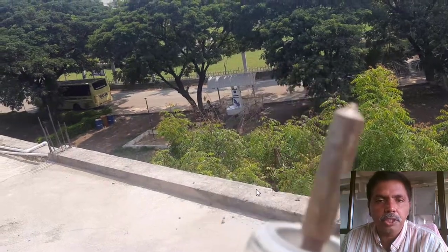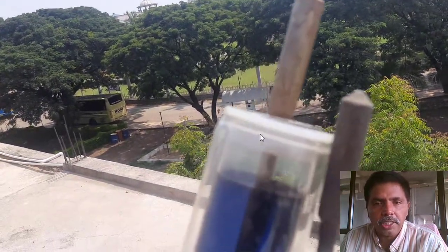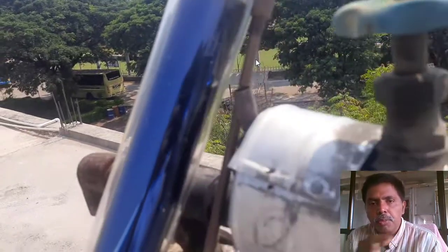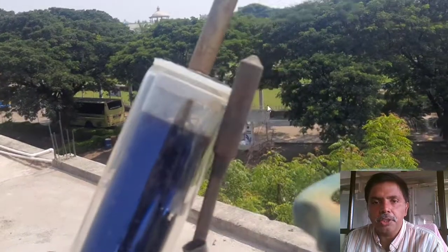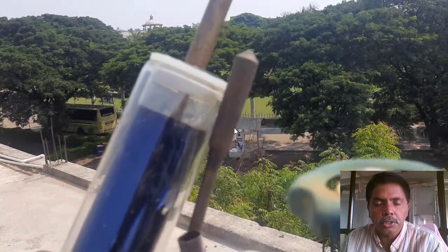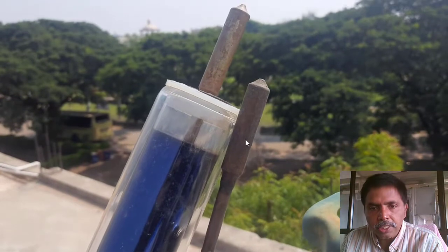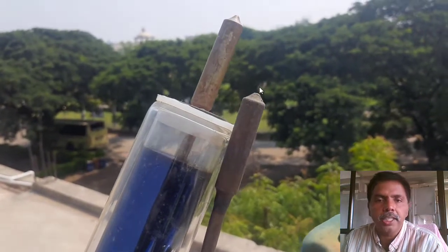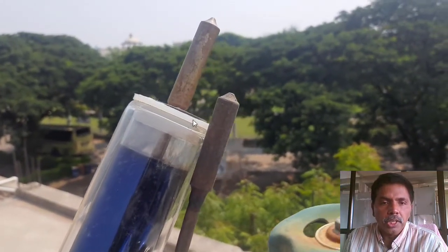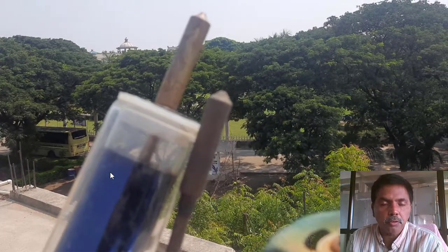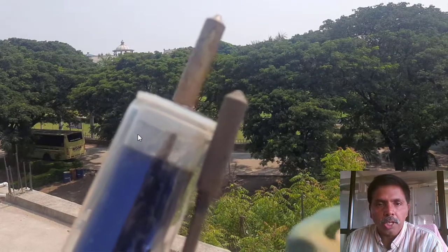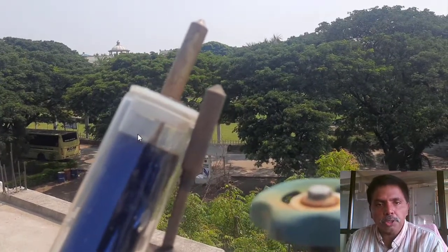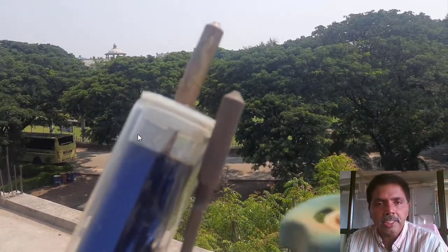ETC collectors are generally used for water heating. For power generation, continuous heat supply with mass flow rate is required. This is the evaporation unit. This is the condenser unit. This condenser unit we place in the manifold. You can see only the condenser unit is exposed to the heat transfer fluid, so the heat transfer fluid is not running through the entire tube. This is the main advantage of the system, and with a particular mass flow rate we can generate the delta T.